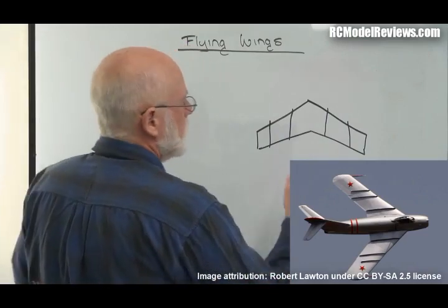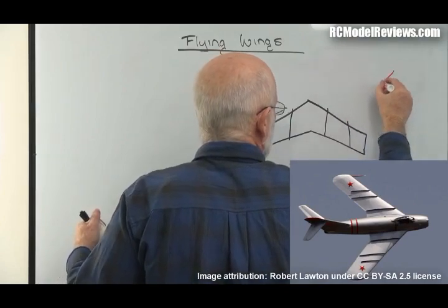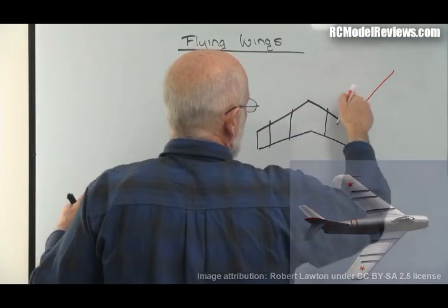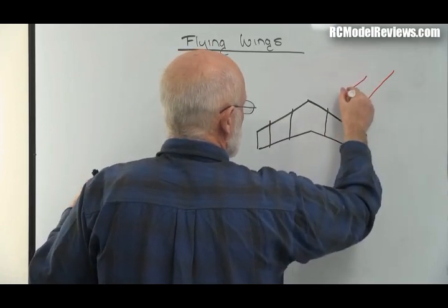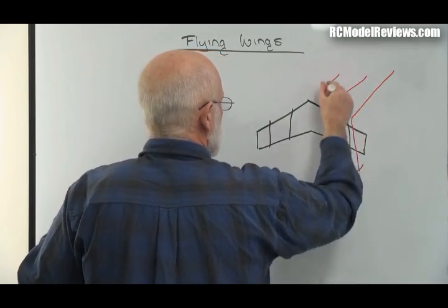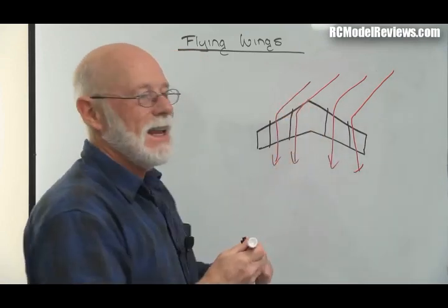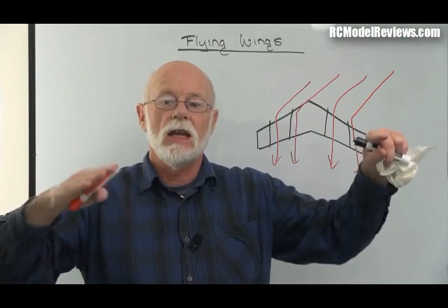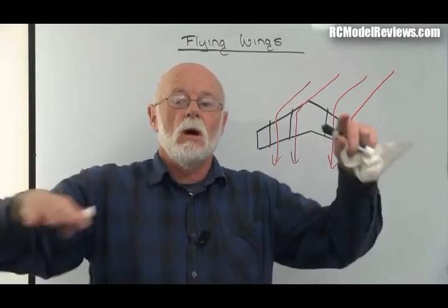And what that's going to do, of course, if we look at it like before, let's say we are side slipping or we've yawed, the air that would normally go straight across here like this and create more lift on this wing is redirected by these wing fences so that it ends up coming off the back of the wing just as if there was no yaw. So you don't get the dihedral effect, you don't get the extra drag, and you don't get the extra lift on that wing, so you don't get the wibble wobbles.